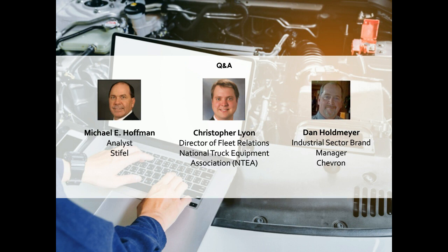But they've gone to the API CK4 and FA4. And now the CK4 oils are the ones that are backwards compatible with previous requirements. If you had an API CJ4 oil meeting the requirements of your engine, the CK4 would meet that requirement. Same way it would meet the CI4 and other previous oils. FA4 oils are only going to be an XW30, so a 0W30 or a 5W30. And they're designed to help the OEMs meet their fuel efficiency requirements, or actually the carbon footprint of their entire fleet. So they've designed their engines to handle these lower viscosity oils and meet that fuel economy.